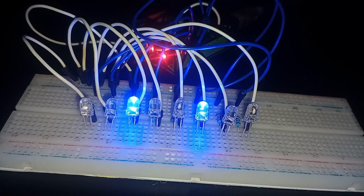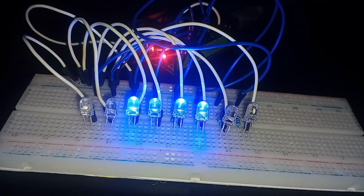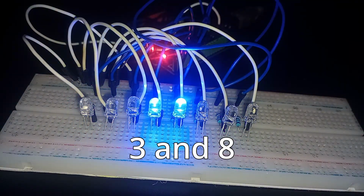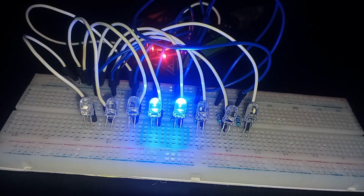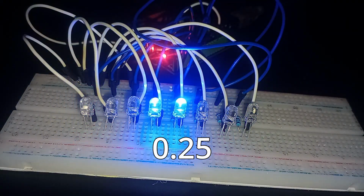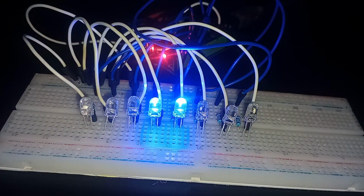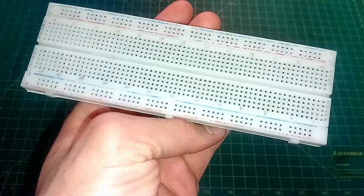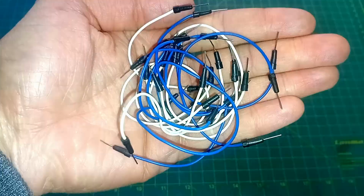First, LEDs on pins 5 and 6 turn on, then pins 4 and 7, then 3 and 8, finally 2 and 9. After that, it reverses: 3 and 8, 4 and 7, and finally back to 5 and 6. Only 2 LEDs will be on at a time, and each pair will stay lit for a quarter of a second. After that, they will turn off and move to the next step in the sequence, and the process repeats forever. For this project, you need an Arduino board, a breadboard, 8 LEDs, 8 resistors of 220 ohms, and jumper wires.